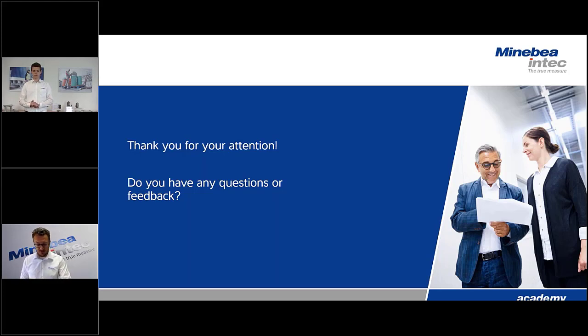So the first question probably is kind of simple. How can a customer or a user determine a possible resolution of a weighing instrument? What should he do for this? Hello everybody again. The highest resolution will depend, of course, on many factors. The first, as already mentioned, will be the load cell, the accuracy class of the load cell, and the evaluation electronics.